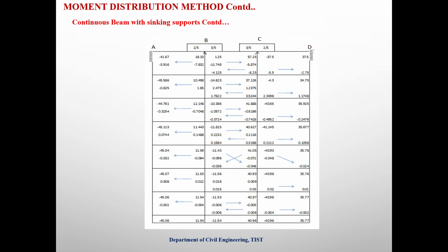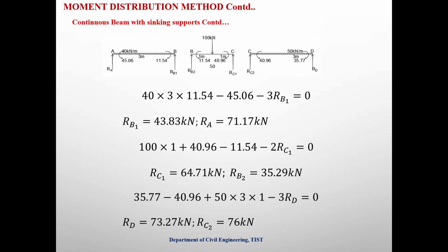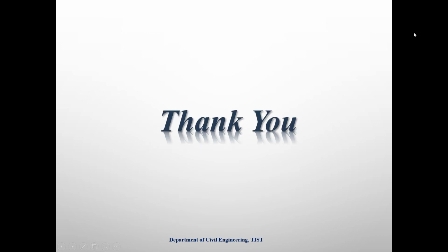After getting the fixed end moment and distribution factor, we can enter all these values into the moment distribution table, and then we can do the moment distribution. And after that, we have to draw the SFD and BMD. Thank you.